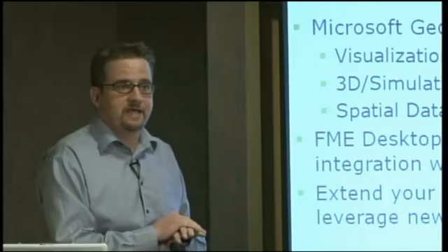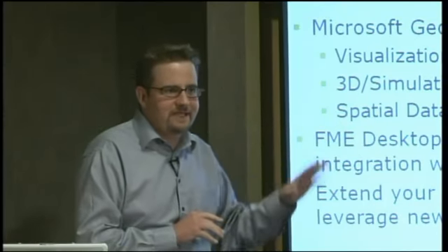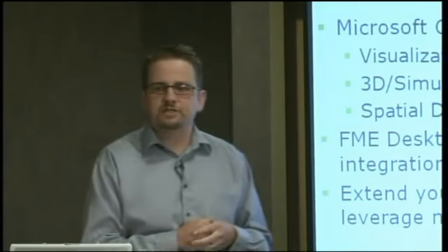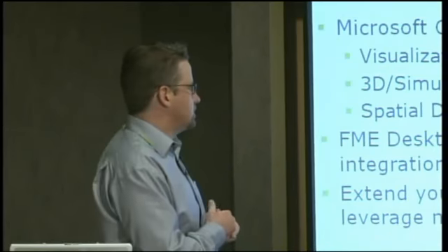And so you can obviously bring these together, use Bing Maps for Enterprise as the base map layers, and then use SQL Server to store and allow you to query and overlay data on top of those bases. FME really provides a lot of cool features to bring these pieces together and bring your existing data together. From a desktop perspective, I use it to take shape files and other content from GIS users and get it into formats that Bing Maps for Enterprise supports, whether that's KML, which is directly supported, GeoRSS, or even JSON files that you can then use with the add shape functions to manually draw each point, line, and polygon on top of the map.